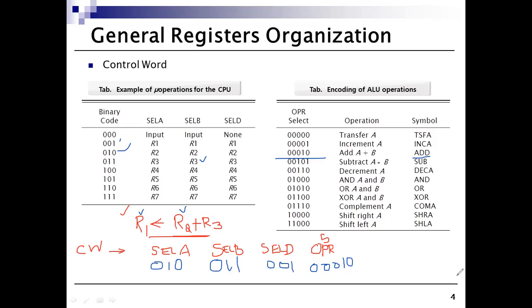Okay. So you require mux A selector lines, mux B selector lines, ALU operator selector lines, and decoder destination selector lines. These 4 control selection variables need to be generated at the control unit, and they must be available at the beginning of the clock cycle for performing the execution stage.